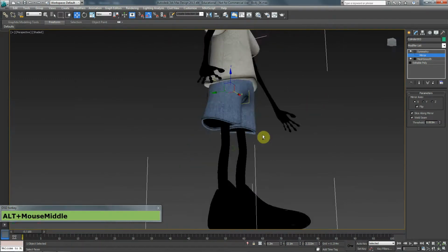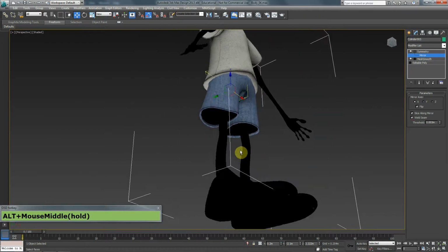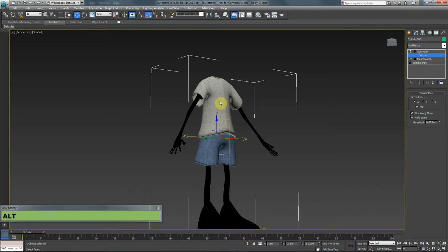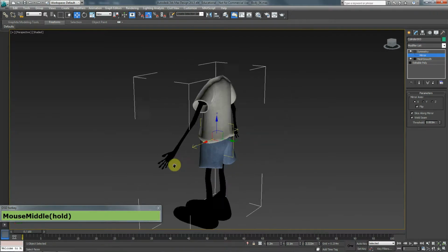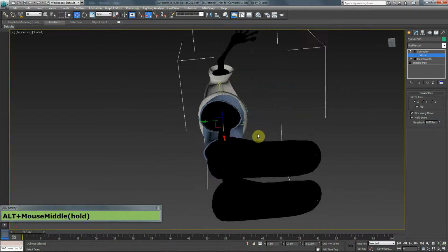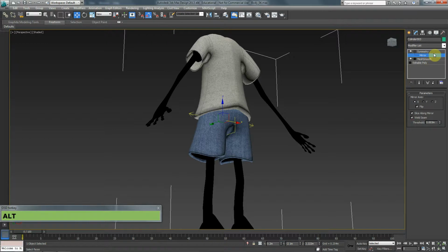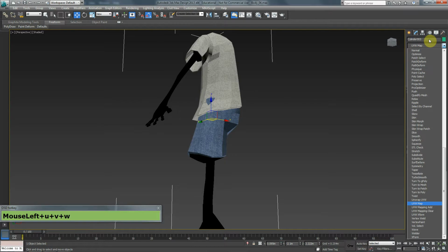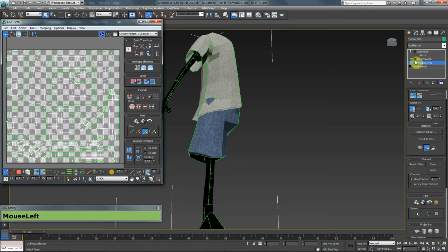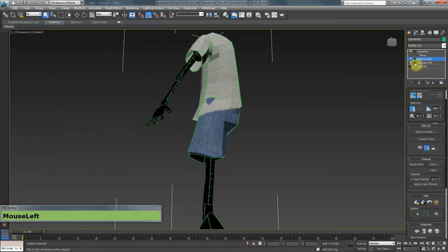Now let's go ahead and find the inside of the trousers, the shorts, and the shirt, and we'll try to texture those as well. So if I was to go here, put an unwrap on top, open UV editor, and go to my polygon mode, face, and select one of the inside ones, open UV editor.